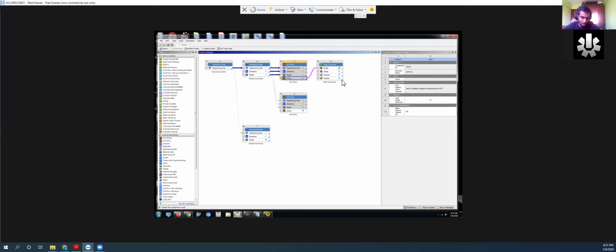So in FEA analysis, there are generally two types of analysis that you can do, very broadly speaking. One is solid, which means you have a three-dimensional element. So you have X and Y along with Z. Remember what I talked about nodes: essentially your nodes connect to each other along the entire structure, and you're analyzing how the nodes react with respect to each other, and that's where you get your analysis from. So your nodes can travel in the X, Y, and Z direction.